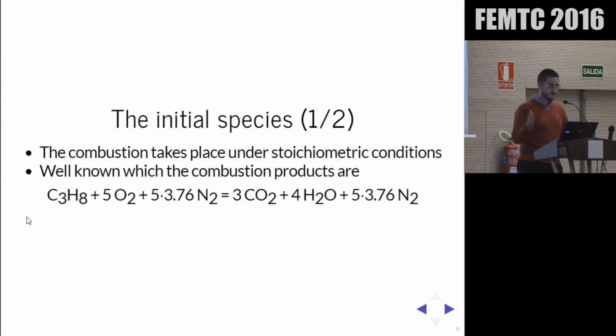As I said, we are having a premixed flame. We can regulate the amount of gas that we are putting in the system, and we can regulate the amount of air, so we can obtain stoichiometric conditions. Just some chemistry from school, and you can know what you will obtain. So you can calculate the products. This combustion product is what we normally call smoke, but we won't see black smoke. We will just see something transparent, and that's the combustion product.